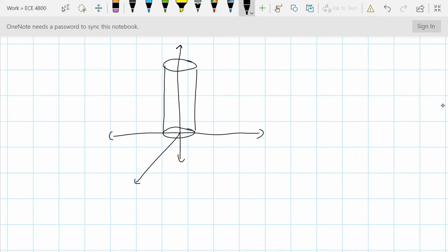And the current density is actually larger on the outsides of the wire than it is on the inside. So that's given by J of R equals 5R. This is one of those wires with strange material properties. And like I said before, this can happen if the wire happens to be doped more highly along the outsides than the insides.